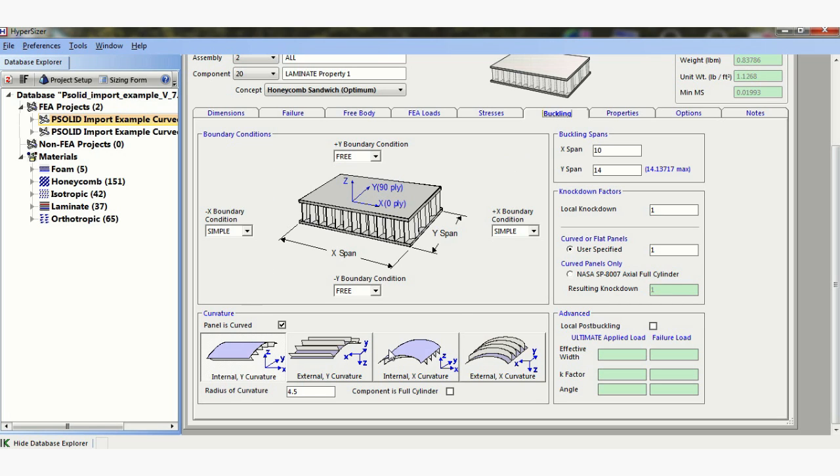So I think this is a really good sheet. It's very simple. I just say what my boundary conditions are. It's very clear which is the X and Y. Very important. That's why you need to understand which is the X direction for the plate, because if you get them the wrong way around, you're going to put the boundary conditions wrong. So it's very important to check that when you're importing your model. You can see here we can have curved beams. I like that. It's good.